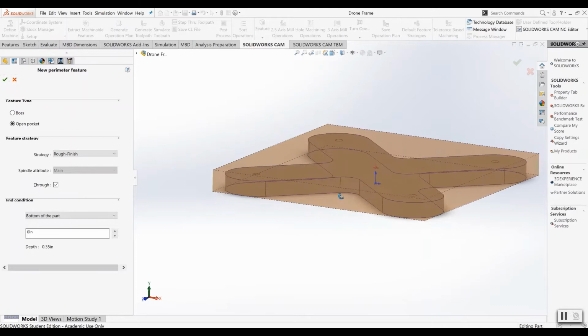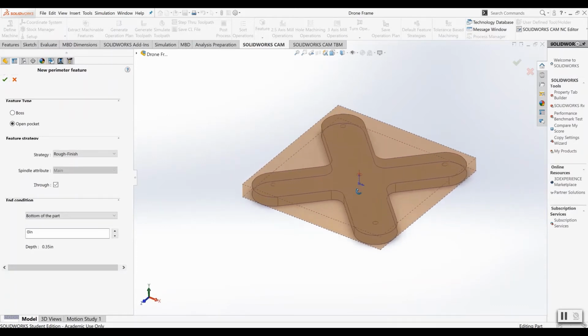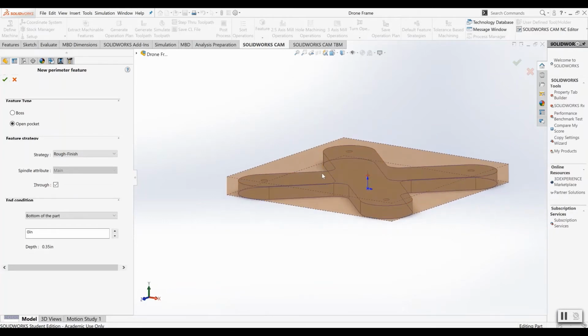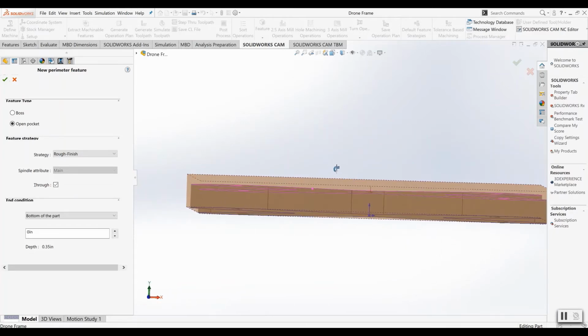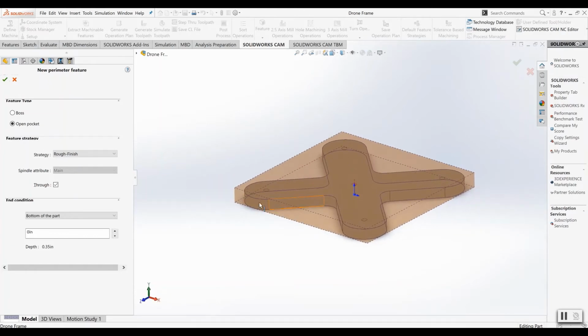So as you can see here, this orange box is the stock piece that we're going to plug into the machining vise shown earlier that we're going to cut. Here's the excess 1/10 of an inch of material that will be face milled off in this process.